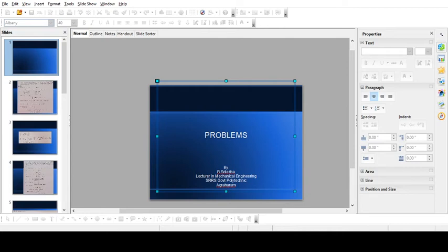Next, we know that strain in the x direction is simply change in length by original length. So the change in length will be 0.357 into 10 to the power of minus 3, and given its length as 120. So you'll simply substitute 120 for L.